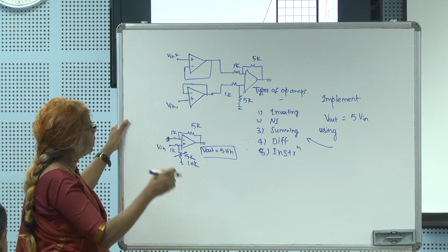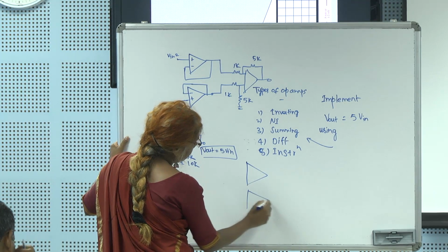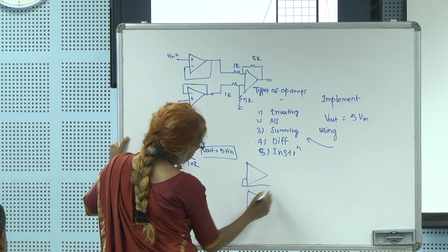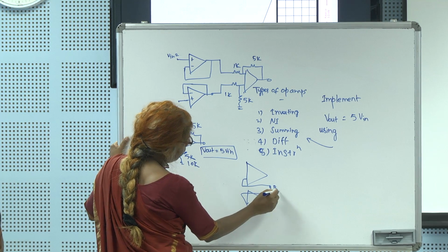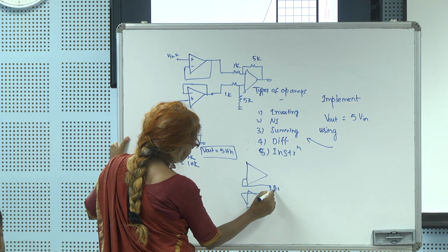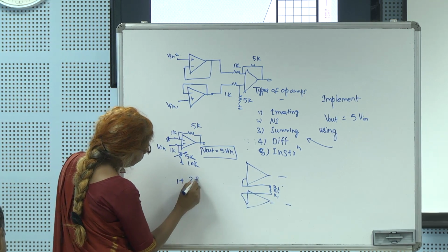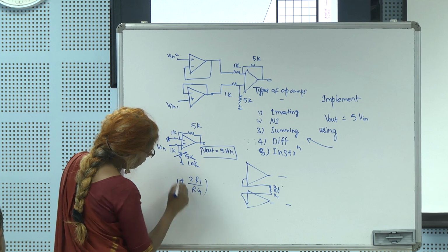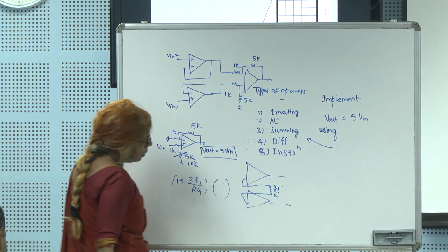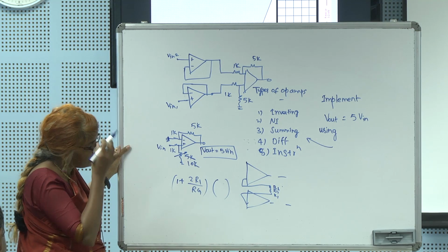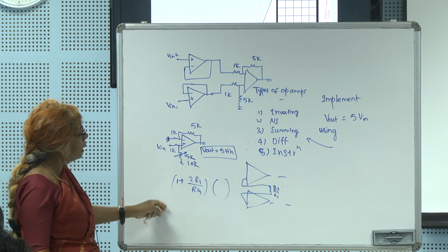That is when that configuration came. Remember, we used that in the ECG circuit, where you will have this one and then this one and then you have the three of them. So it is R1, RG, R1 and all those things. So, we have 1 plus 2 R1 divided by RG as the pre-amplifier stage gain, then comes the differential amplifier, then the high frequency filter, then the low frequency filter and then another stage. You understand? So, this is the instrumentation op-amp.